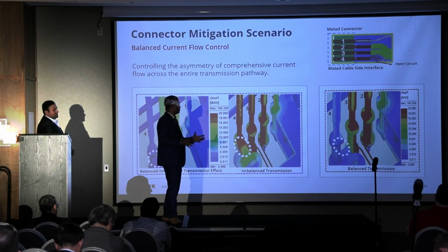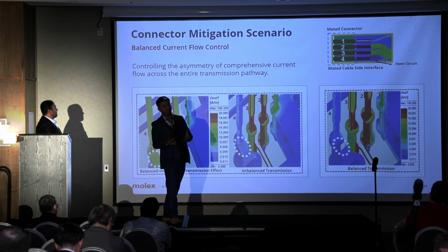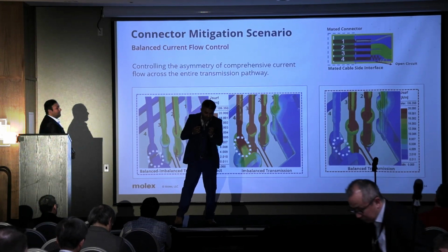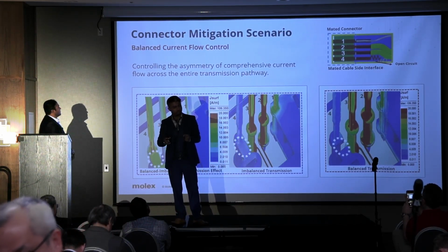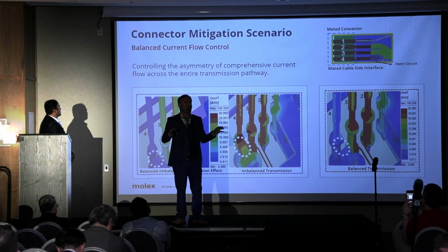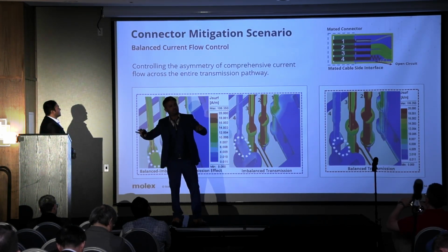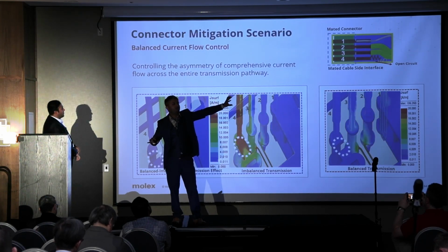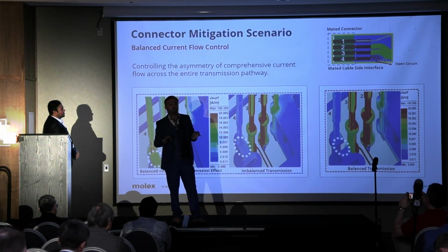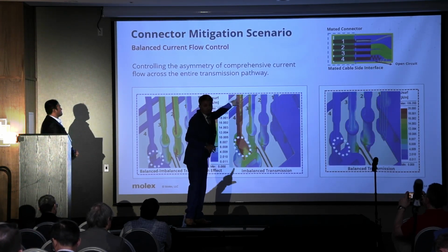But many times we will be creating an unintentional radiator or an accidental radiator. And the main thing that creates this kind of accidental radiators are impedance mismatches between the source and the load. If a source is driven by a very low impedance, and there is a very high impedance at the load, this is one of the key parameters of creating an accidental antenna, and that is what is happening in pin number 4.